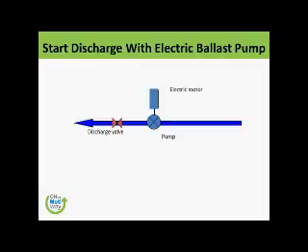So it is better not to start the pump when the discharge is open. When you're starting the pump, the flow will go and the pump will trip. So we need a back pressure.